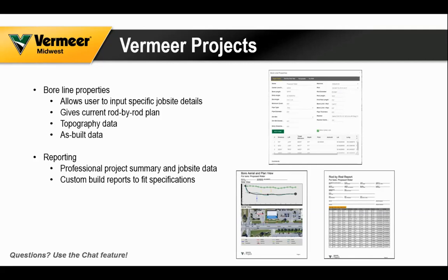It has the ability to manually bring in topography. Say you didn't map it and you used the Google Earth, but you had some better topography information than what Google Earth was giving you. You can pull that in here. And it also allows you to do manual as-built. So if you don't have the Falcon or are unable to bring your LWD files straight in, if you're recording as-builts on paper, you can come back and put those in here for a reporting aspect.